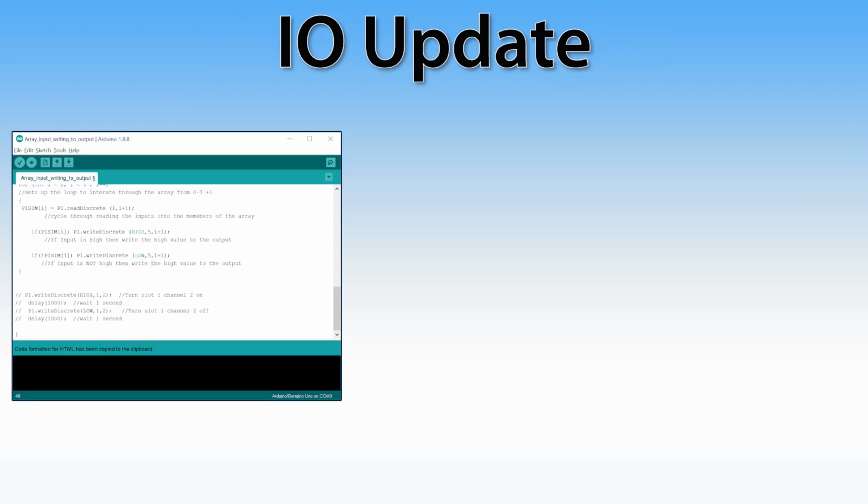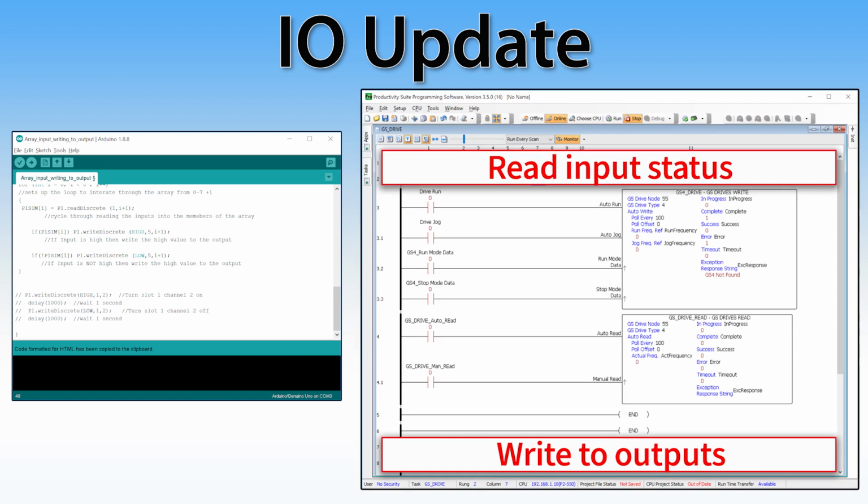All I/O is immediate in Arduino. When you turn something on in a line of code, it happens at that moment, whereas with most I/O in PLCs, the on or off condition is handled at the end or the beginning of the ladder scan, with only some specialized I/O being immediate. This is neither negative or positive, just handled differently. Just be aware that there are some differences that may cause a little confusion in your timing routines.